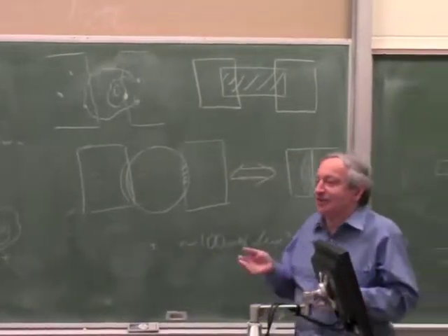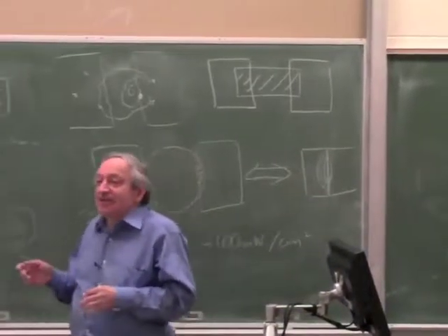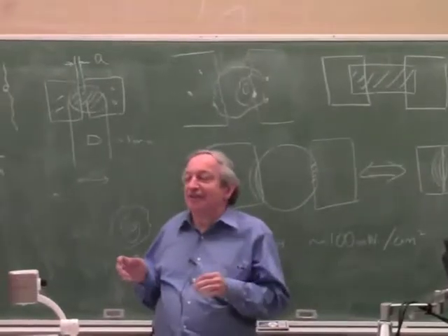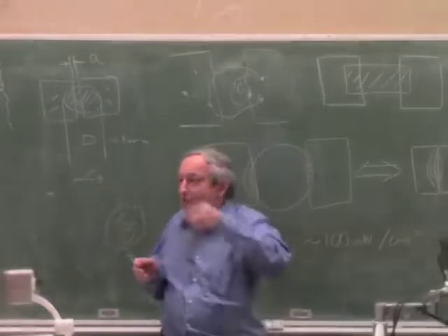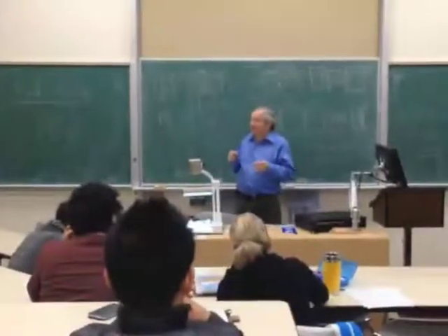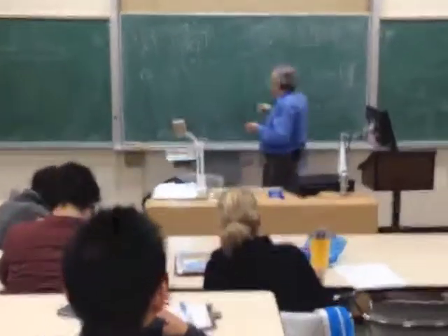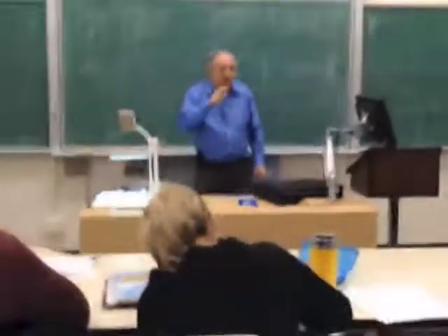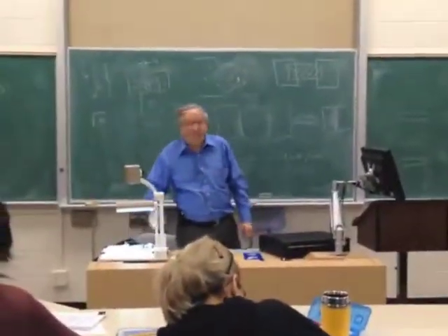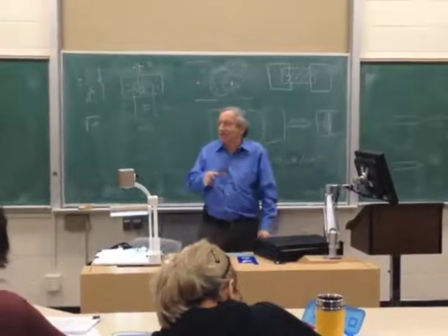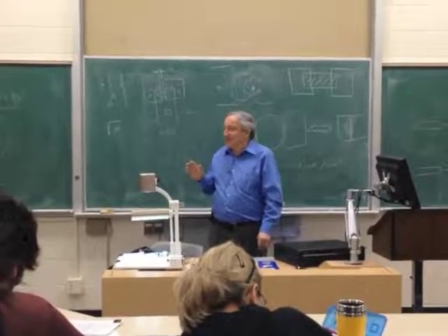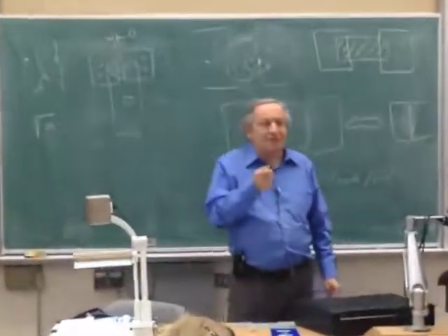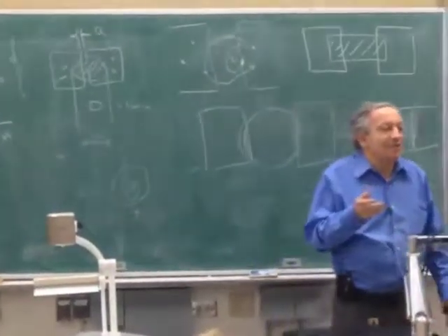When you think of a detector, you always think it's linear. But it saturates. The same thing, by the way, can happen in an LVDT, but it's less likely, because theoretically, in an LVDT, you can run the excitation coil. It's much harder to saturate the magnetic material in air than it is to saturate the silicon detector. So remember the rule of thumb that a laser pointer pointed at the silicon detector, even a cheap red laser pointer, is already saturation. So that's already not safe to do with an accurate sensor. But even with a normal laser pointer, you have to expand the beam maybe to 10 millimeters to be absolutely sure